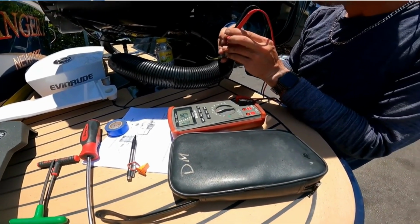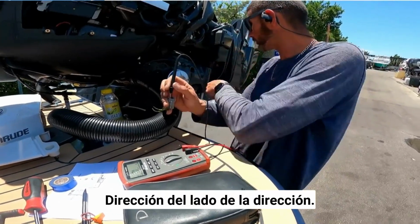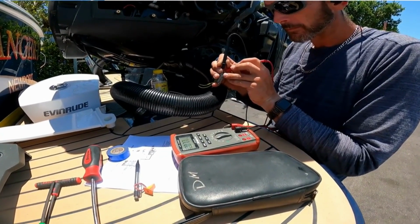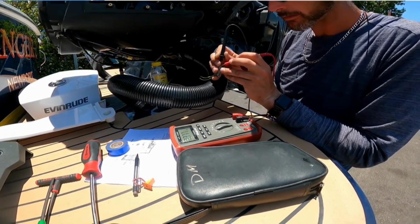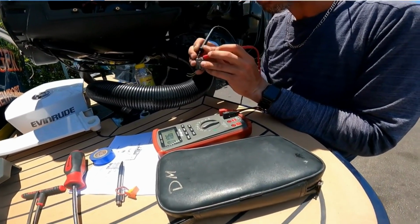Okay. Which solenoid? The directional ones for the steering system. 7.8 ohms. It's low. In between, it's 10.6.